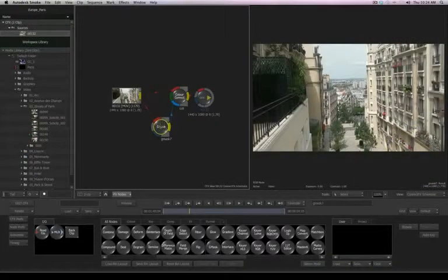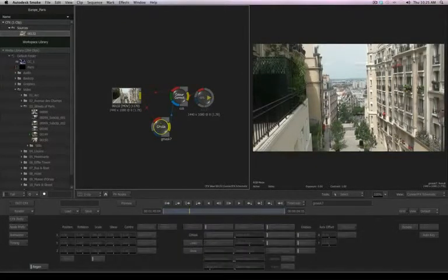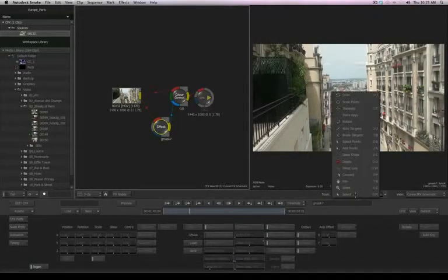Another tip for you to access the parameters for any tool without having to come down and click the FX node to discard my bin is simply double-click on a node. So I double-click on this garbage mask and you'll notice the garbage mask parameters become available to me. Since the schematic view is enabled currently, you'll notice that all the tools and parameters for my garbage mask are grayed out at this time. The tool option is available though, and if I expand that, I could choose Draw Shape or use the shortcut of Shift-C to access this tool.